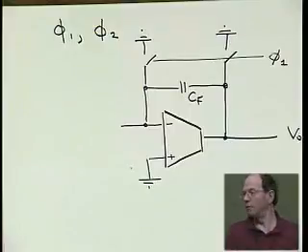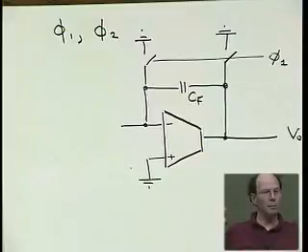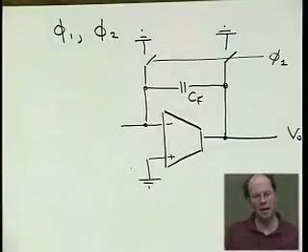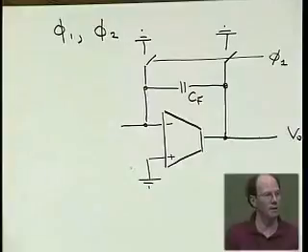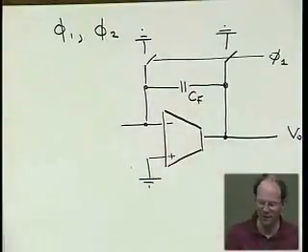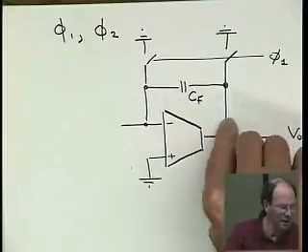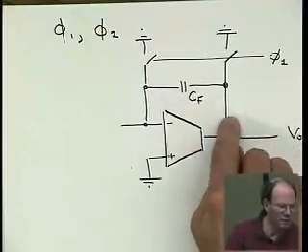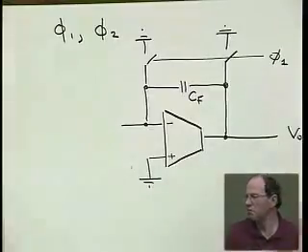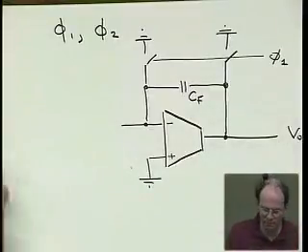It's actually good that we short-circuit the output, because otherwise a current source has got to spit out its current somewhere, and if it cannot spit it out, then all the levels inside the amplifier go haywire. So it's actually a very sensible thing to do. Of course, if this was an op-amp, forget it. You will need an extra switch here that opens during phase 1. So that switch would be labeled phi 2. But here, just fine. Right?